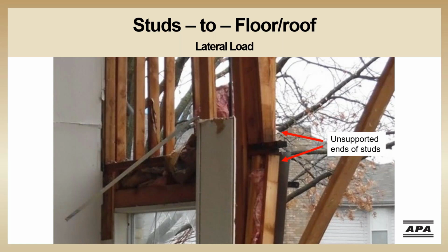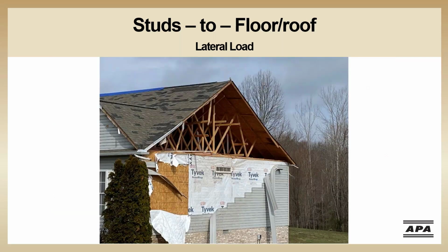Here's a close-up of that detail. Platform framing, as seen in this photo, is only appropriate where there is a floor system to support the studs. Another common location where we see this type of load path failure is at gable ends.